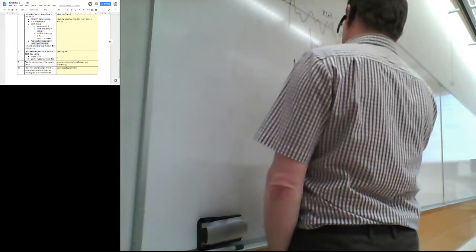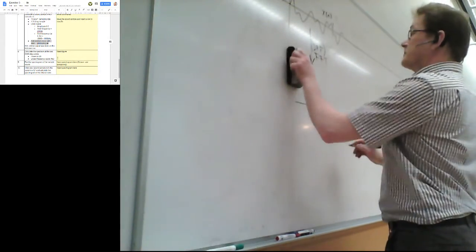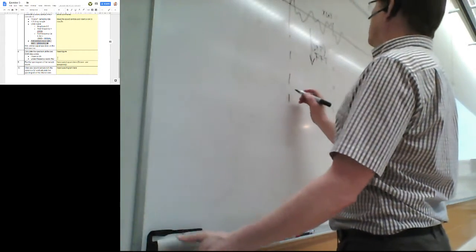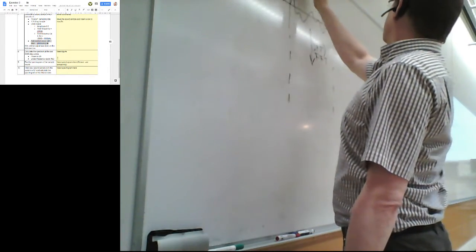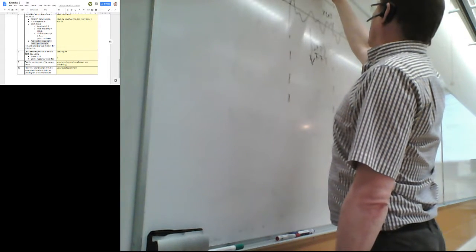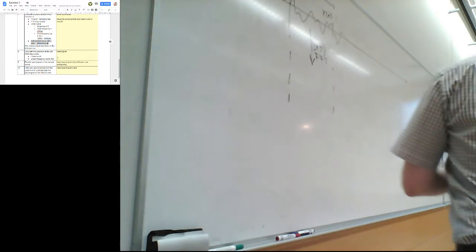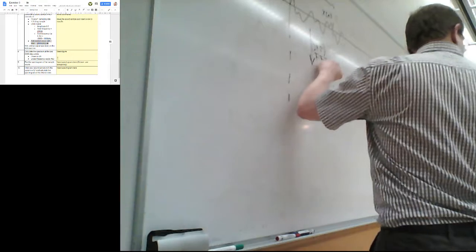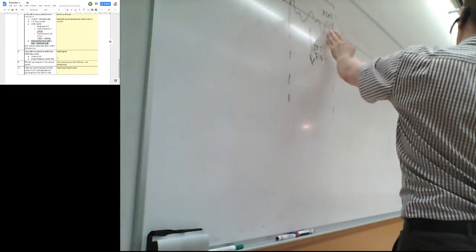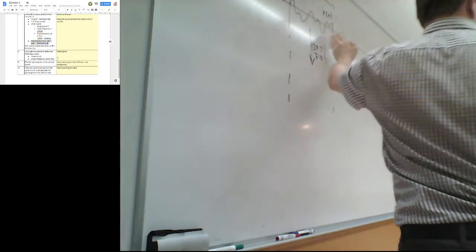But anyways, when you do the discrete Fourier transformation on that block, first it means that n must be 2 to the power of something. You need that many data points in order to use the FFT. If you have fewer, you can do zero padding to achieve the same resolution.